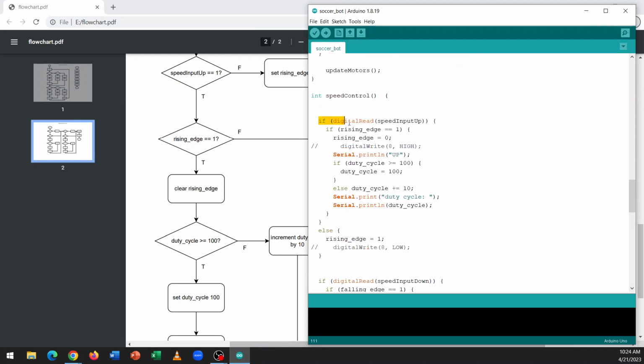So if you go into the main function of the code, you can see here. Again, we're going to use a digital read to constantly read the value of the pin to say whether it's high or low, because when a button is pressed it becomes high, right? So when a button is pressed, then you check if it is the noise or not, and if it's not the noise, then you set it to 0 again to make sure that it can detect the next one.